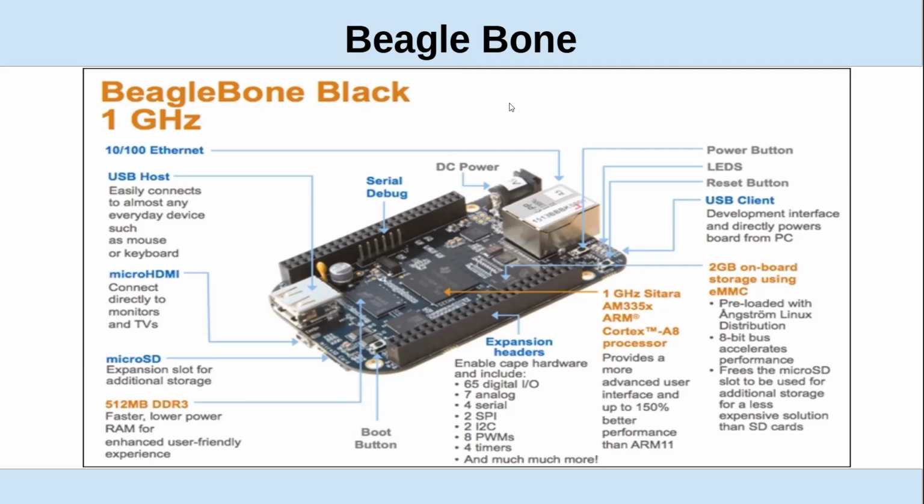The BeagleBone Black was sort of the entry one that was the beginning. It again uses the ARM chipset, similar to what's in the cell phones and things. The interesting thing and why this was very popular for CNC is it has what they call 2 programmable real-time units, which are 200 megahertz RISC processors on it, in addition to the main CPU.